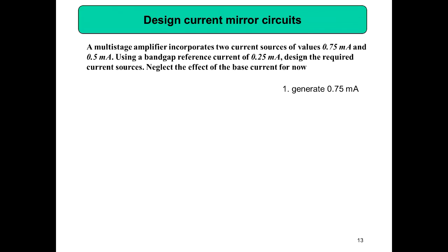Yep, that's correct. So 3 transistors. First, this is a current mirror. We have VCC, then a 0.25 milliamps I reference. This is a golden current, the current from the band gap reference. So 0.25 milliamps is coming, and using this circuit we are generating an I